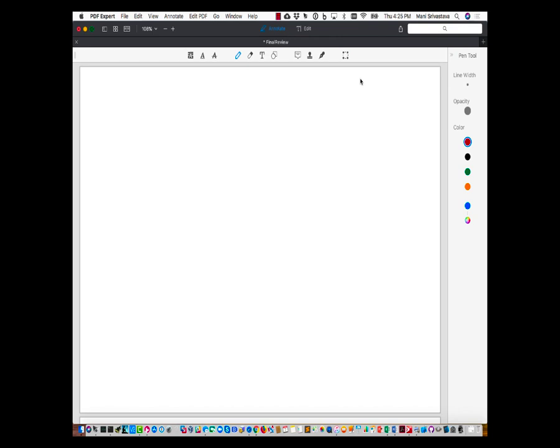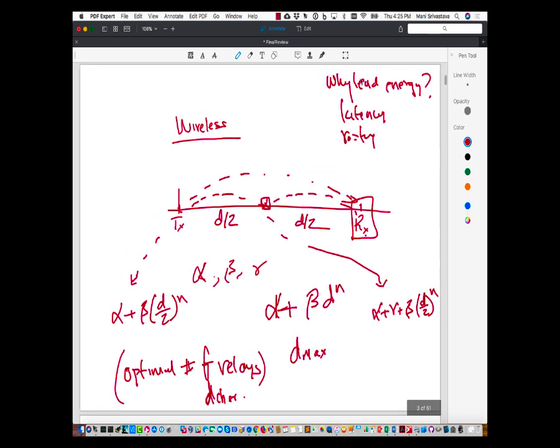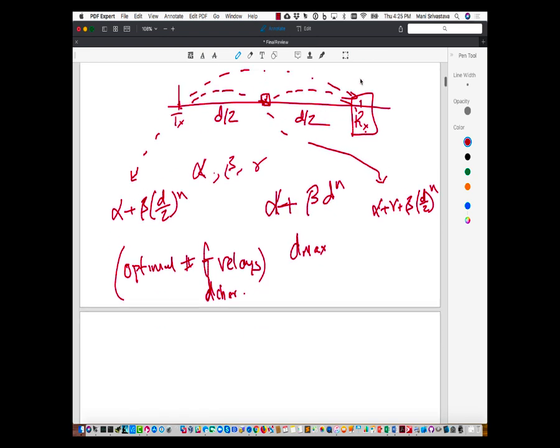So that's why you have an optimal number of hops, in the sense that if you increase the hops, then even from an energy perspective, you're worse off. By the way, another thing to note out here is that these relay nodes become the bottleneck. And if you think in terms of a network, which relay nodes are going to be the bottleneck for the network? The ones which are closer to your sink, right? Because they are going to be receiving everyone's traffic. So that becomes an issue.